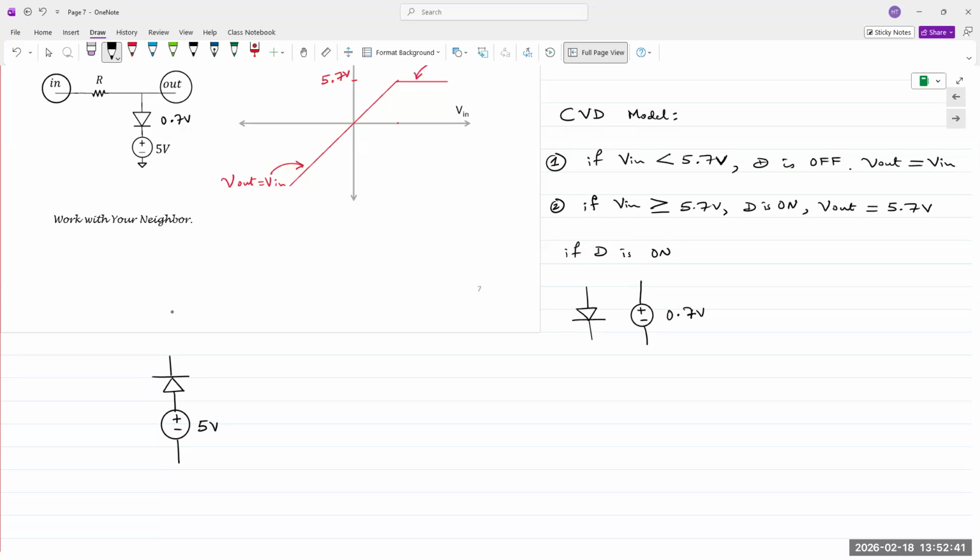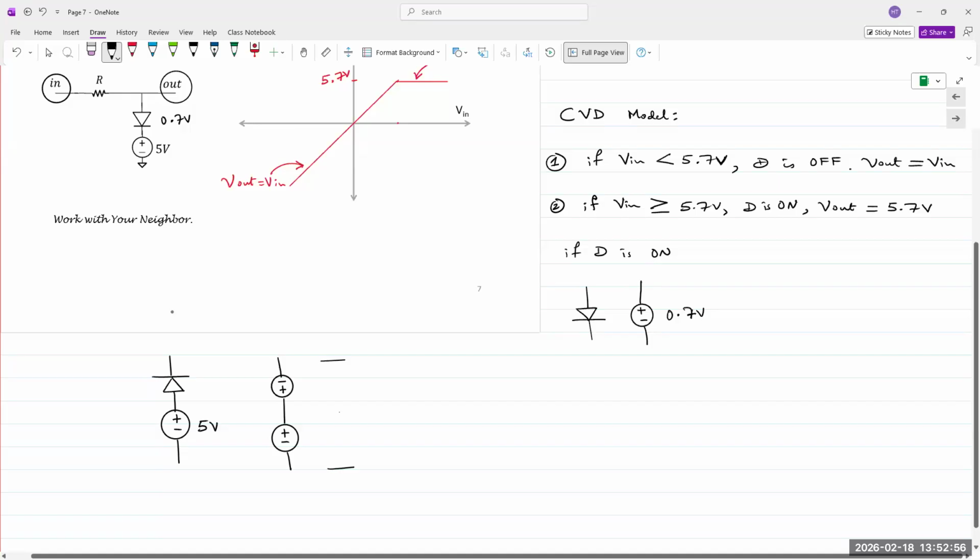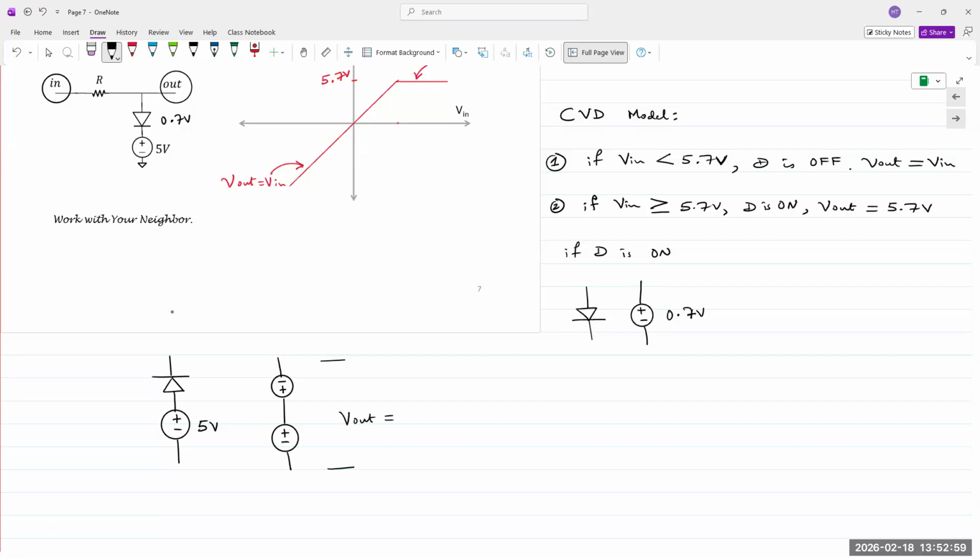And when the diode is on, let's say in this case, the voltage would appear like this. And if I was to take V out here, this V out, you can apply KVL and mathematically write any expression, but of course, this would simply be 5 minus 0.7 or 4.3 volts. Because this would be 0.7 in opposition to that 5-volt source. Yes.